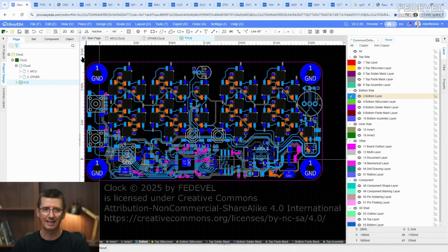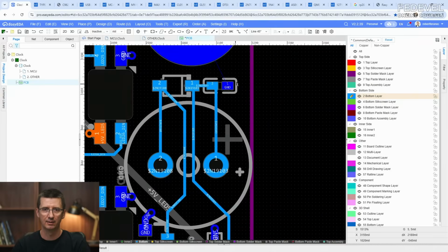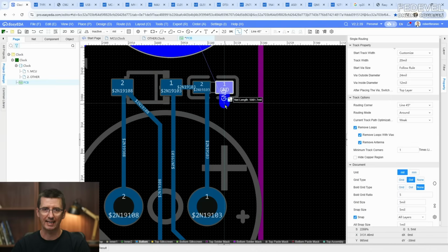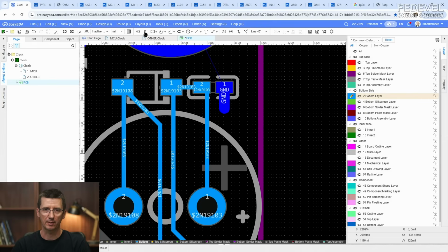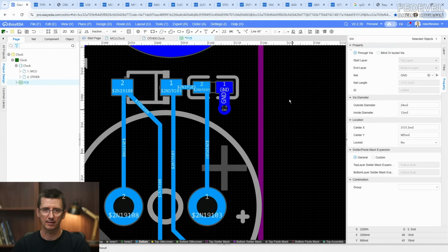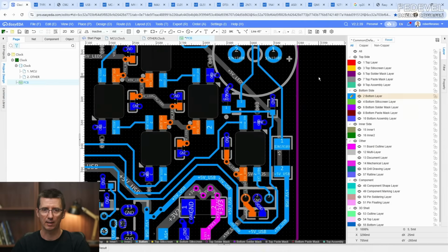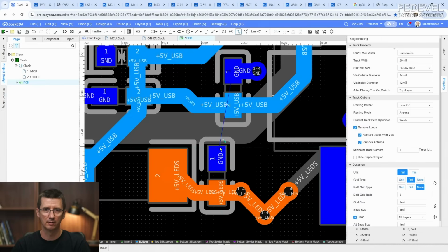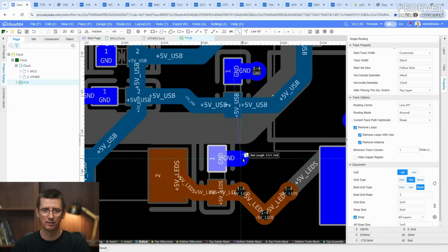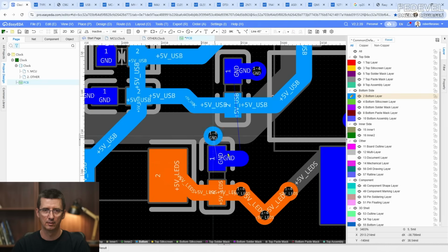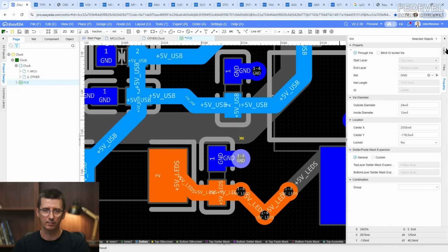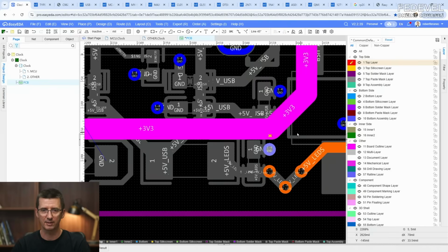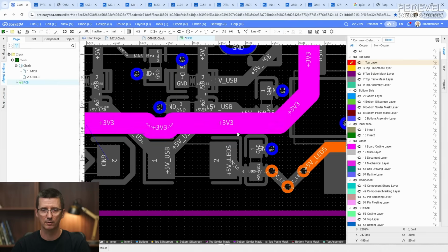Because they call it an acid trap. So when they are etching the PCB, acid can be trapped in these sharp angles, and maybe later it can cause problems. Or maybe even during PCB manufacturing it can cause problems.